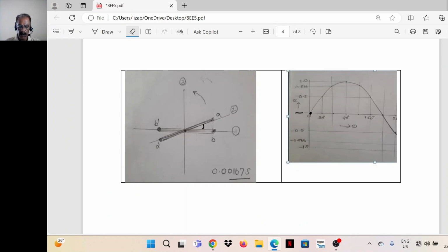Now assume there are two sets of coils, A dash and B dash. Both are identical coils, fixed at an angle, assume an angle of 30 degrees. And the set of coils are rotating in the counterclockwise direction. Now let's say what is given in the figure is the voltage induced in coil B. In the direction of rotation we are considering it as anti-clockwise.